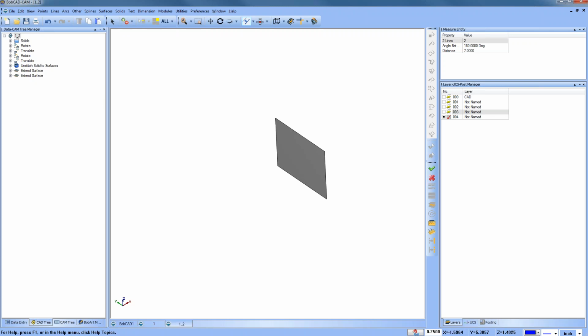Let's see here. Do you need to have a part drawn in 3D to get a taper, or can the path be created with just a 2D drawing? Linda, you can do a 2D drawing, so that's not a problem at all. I have solids here because it's easier to see what's going on, but you can do land and taper just based off of wireframe, flat drawings. You can do 4-axis programming based off of flat drawings as well, and I'll get into that.